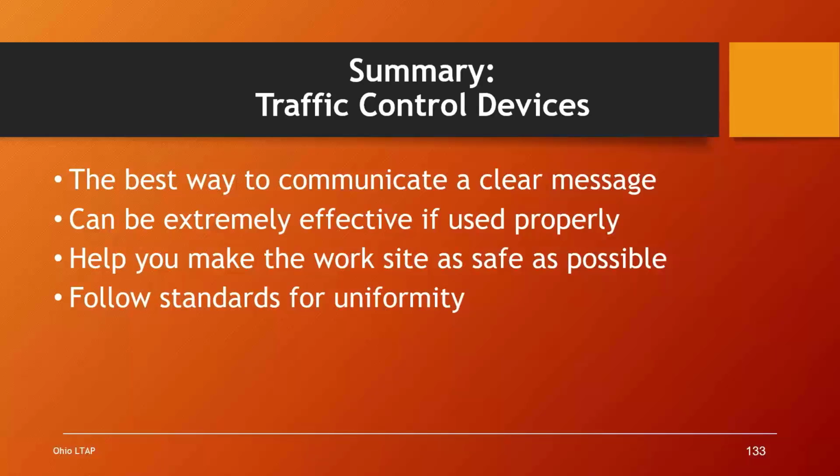And I can't stress enough that as we get later on into our different sections, maybe I'll be asking you to design a work zone in a particular situation. You don't just look at the picture in the typical application. You need to read the notes page, because in the notes page under standards, guidance, and option, there might be other temporary traffic control devices that you need to use.